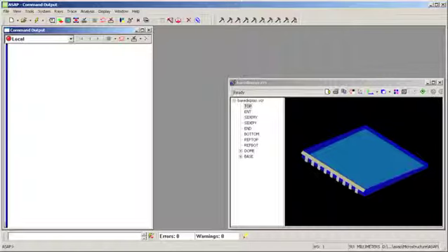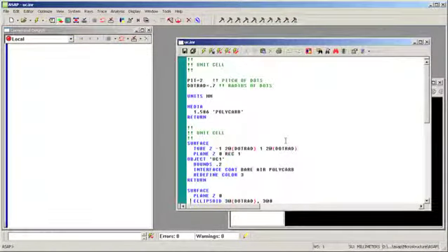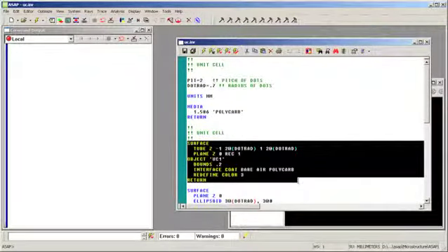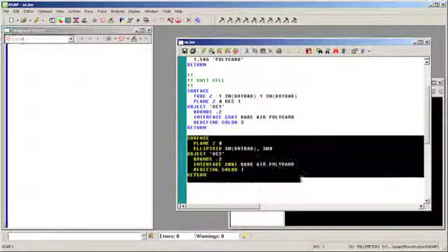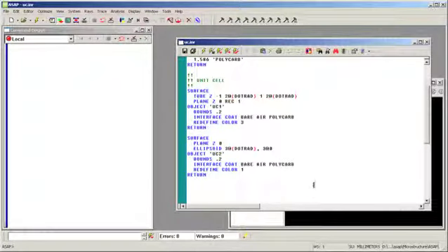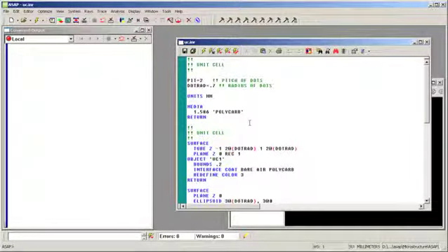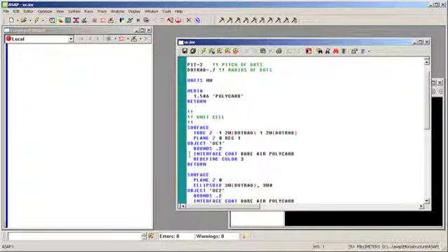First, we construct a single unit cell, centered on the origin, with the z-axis normal to the rectangular boundary of the cell. Here is a script that defines the unit cell. The rectangular boundary that surrounds each hemispherical bump is given here, consisting of a plane with a cutting tube that cuts a circle that allows the hemisphere to fit inside. Below that is the hemispherical bump, shown here. Note that we define not only the geometry, but also its optical properties. We define a media, and we apply that media to each object using the interface command.